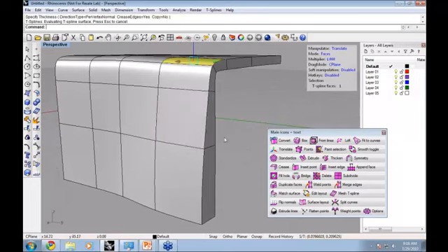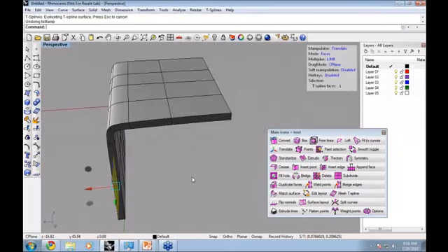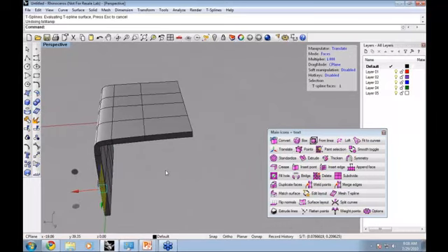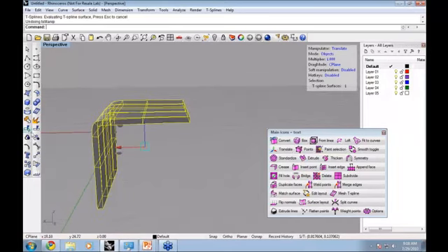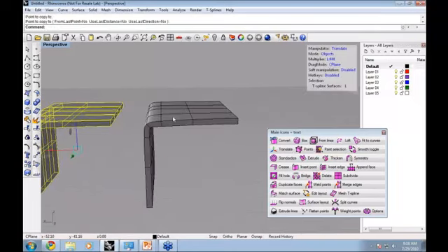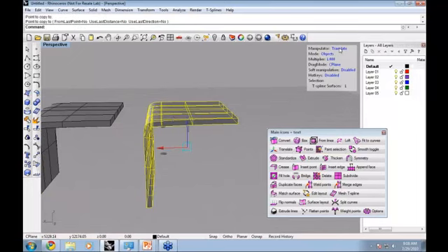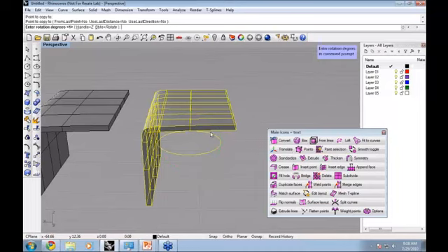So now let's take a look at the bridge command. And to do that, I'm going to make a copy of the T-spline. Let's go to object mode and copy, and then I'll just go ahead and change to my rotate manipulator. And if I double click one of these rotation rings, then I can enter an exact rotation distance.